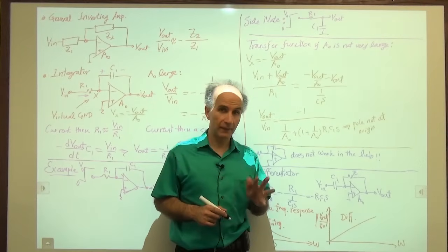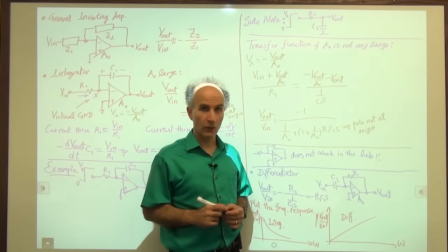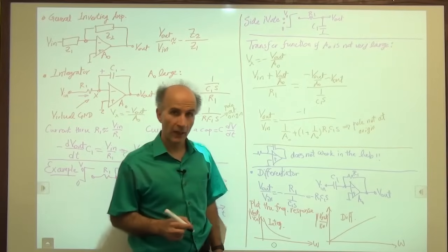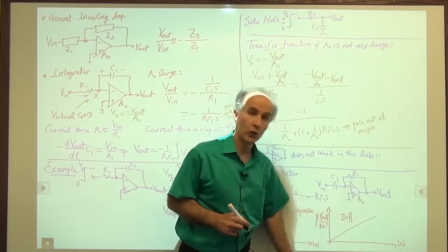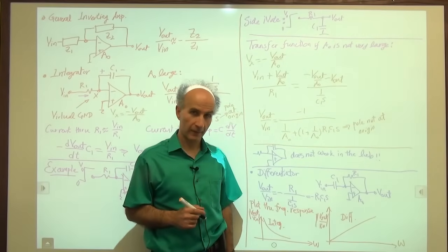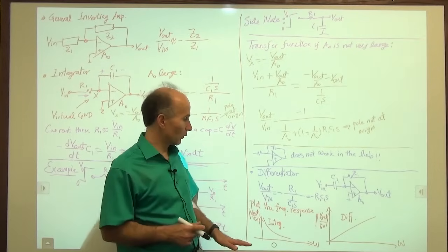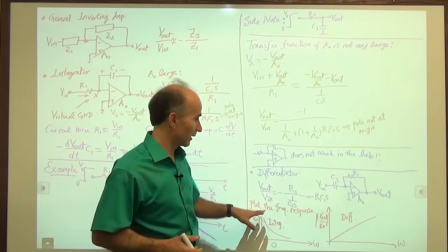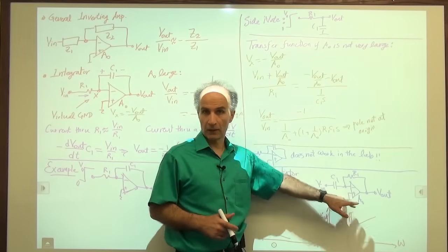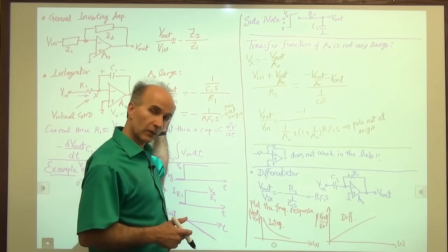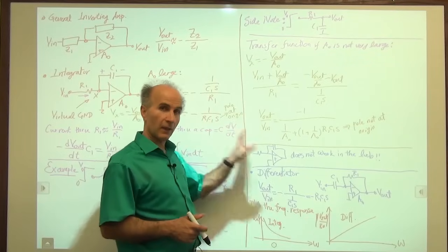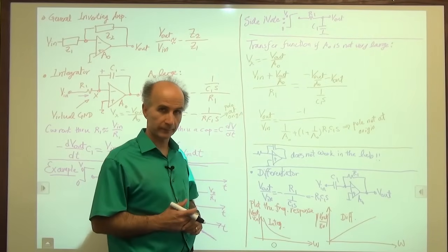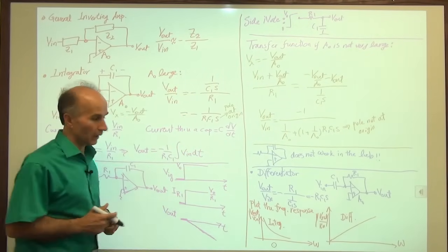We try to use only integrators if we can, so as to avoid this problem of high frequency noise amplification. And for that reason, we won't study the differentiator in other cases, or when A0 is not very large and all these other things, because the integrator has much more application than the differentiator. All right.